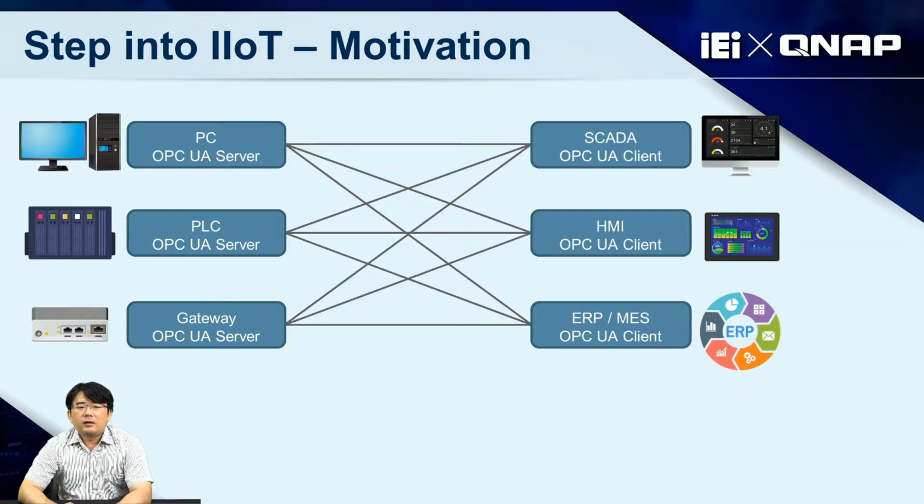You can effectively reduce the delay time, and the PLC doesn't need to provide multiple client requests, and the traffic control can be generated through the QIoT OPC UA gateway. Data traffic can get more throughput and provide more connections. The data systems, SCADA, HMI, ERP can get production information fast.